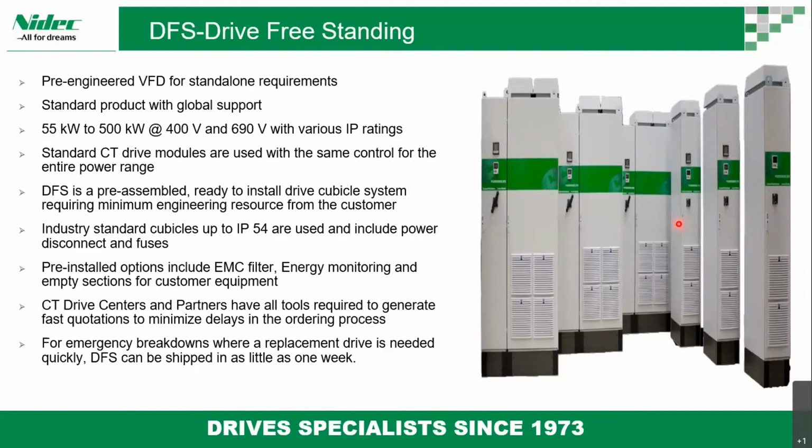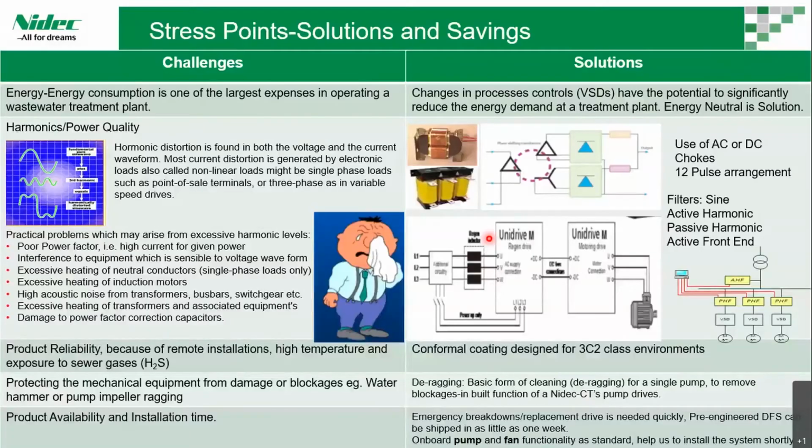So the reason we came up with the other product, the drive freestanding, is that it's a pre-engineered VFD for standalone requirements, from 55 kilowatt to 500 kilowatt. We came up with this product specifically wherever there are emergency breakdowns and a need for replacement drives quickly. That drive gets shipped to any region of any country, as we have a setup in all the drive centers. We can go up to IP54, with an inbuilt EMC filter and an energy monitoring section for the customer equipment. This is one more product we can offer in this sector, water and wastewater.